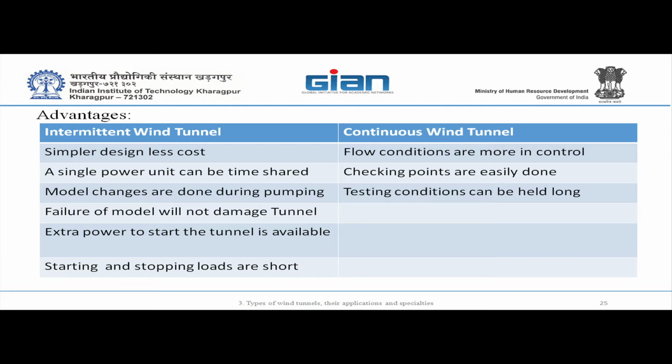So in case of the pressure driven blowdown, we'll have a pressure regulator to reduce the storage pressure, your settling chamber pressure, so we can regulate the complete blowdown. In case of in-draft vacuum, you can also regulate on the back pressure. The entry is always atmosphere, the driving is almost the same. You just regulate the back pressure.